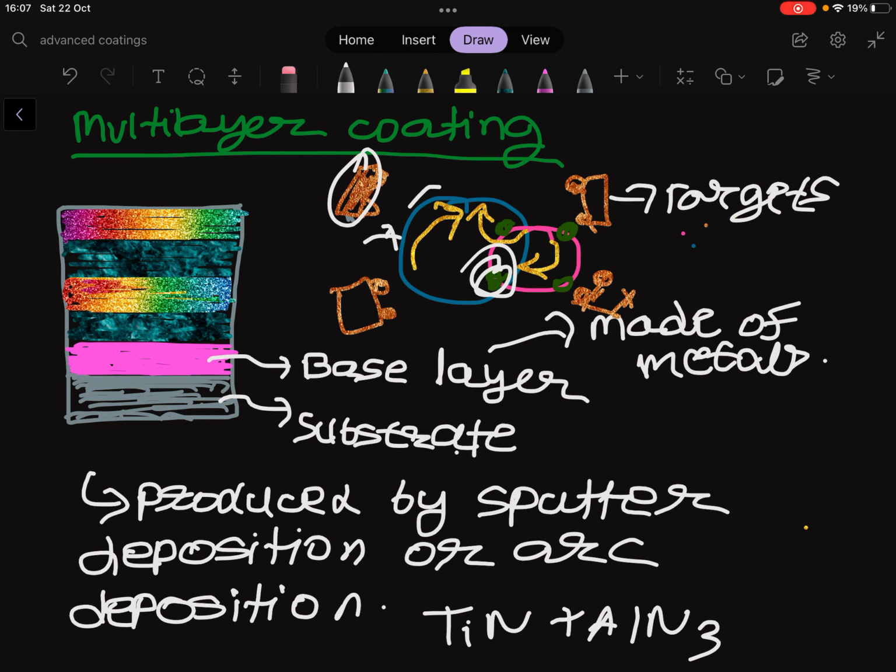And then we can apply the general concept we know for metallic materials. So if we create a thin layer where this distance is comparable to the layer thickness, we need a shear stress which is proportional to the reciprocal of this thickness. So a very thin single layer will impose a very high shear stress to move this dislocation inside. So the deformation of this overall coating is governed by the thickness of a single layer.